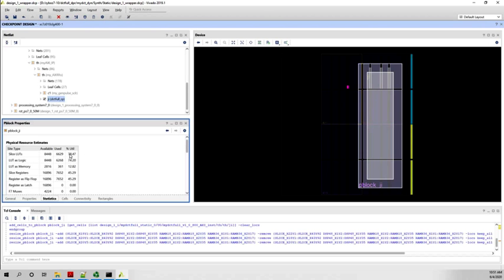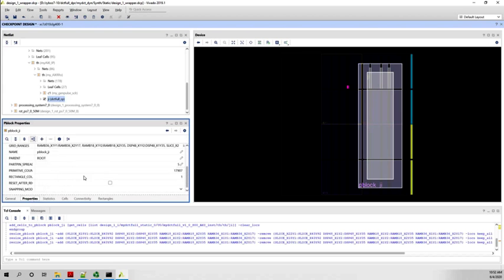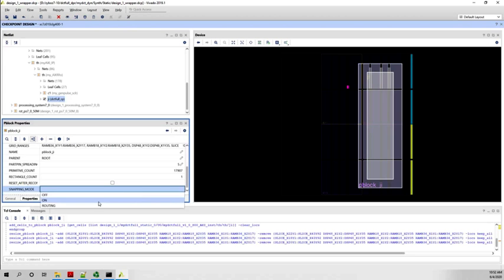One important thing here is the following property. If you try to run the DRC now, you will get a lot of errors about this being located on a wrong left edge or wrong right edge. You can avoid all of that by going into snapping mode and selecting on.